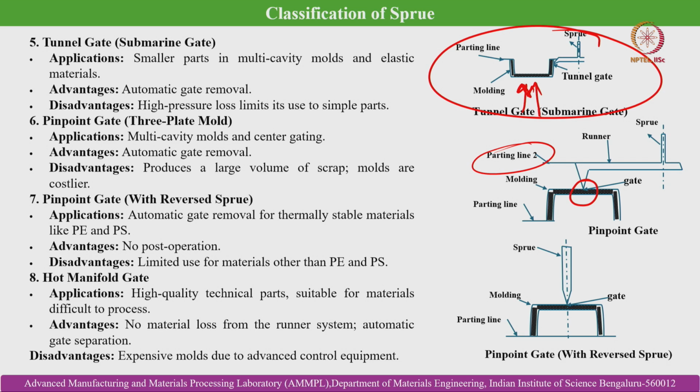So, these 3 part molds are only useful for very complicated components, complicated micro components, where there are multiple cores, and also these cams are needed to move the ejection mechanism. In that case it is not possible to house the entire system effectively in only 2 die halves. That is why another die half is generally introduced.